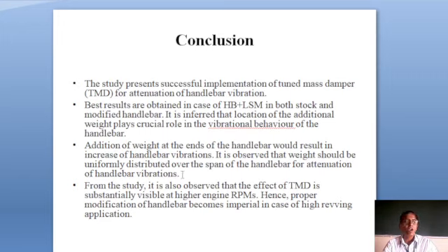Most of the people use bar ends to reduce the handlebar vibration, but in this study we have observed that merely adding a weight at the bar ends, at the end of the handlebar, would actually increase the vibrations, and it is not recommended that you put the bar ends on the handlebar.